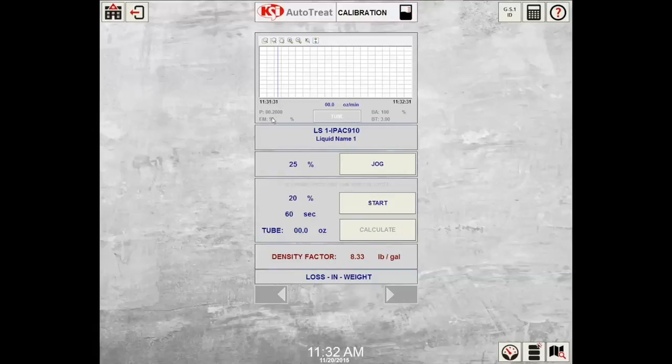The EM, right underneath that, is the effective max speed. Whenever the pump hits this speed, the system automatically forces a pump fault and a system pause. Typically, this is set between 90 and 95%.